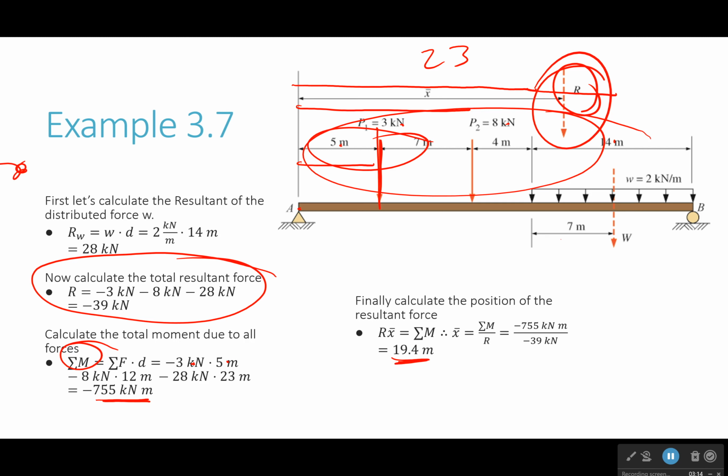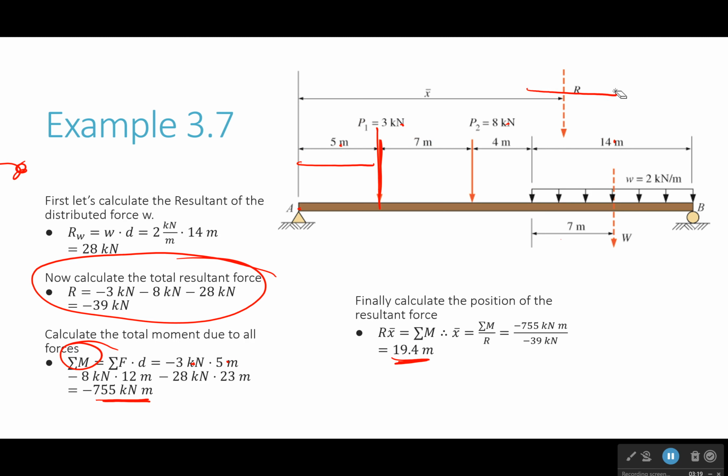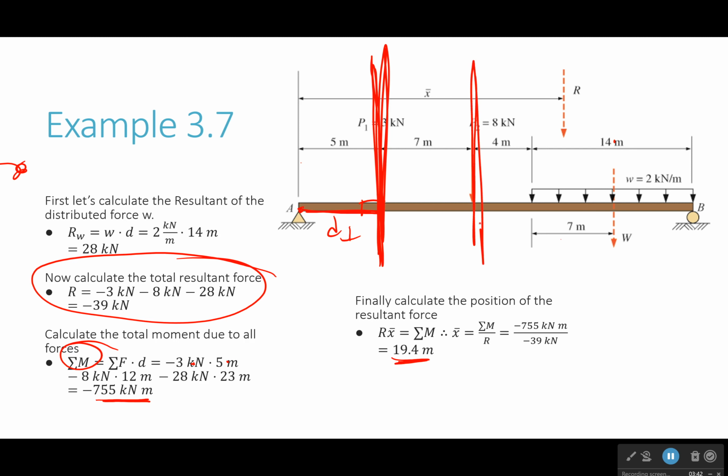Okay, so that's it. That's how you do these problems. It's just a few steps, but you have to master them. And I would say that probably the biggest issue for a lot of people is going to be the moments. A lot of people struggle with moments. It's a force times a perpendicular distance, okay? So you draw that line straight through your force going up and down, and you say, okay, from this point, I'm going to draw a line straight over to it that's perpendicular. What is this distance? What is that perpendicular distance? That can help. Do that for all of your forces if you need to. And if you have a force that's at an angle, then break it into components. Break it into components and then redo it with the vertical component and then the horizontal one.